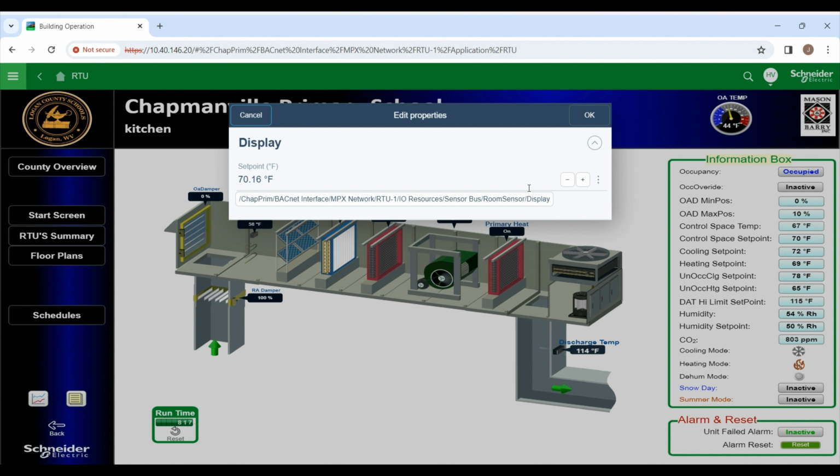Right now, you probably have it between 68 to 74 because we had some complaints in the past saying, okay, this is hot, this is cold, whatever. So 68 to 75 is the limits that you have. You can call me and say, hey, I want all the schools to be, for example, 70 to 74, because again, it's adjustable. You can change that, but not from here. It's got to be from the actual system. I'll show you that part after we're done on the actual software. All we can control is that limit.